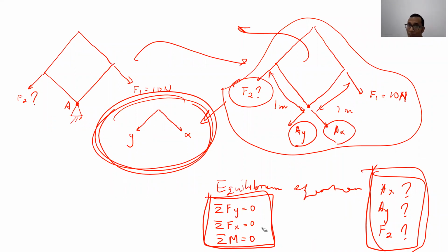Without moving the force, actually, you can solve this using sigma Fx equal to 0. Sigma Fx equal to 0 means that the total force in the x direction will be equal to 0, right, Marsha? Yes, sir. Would you mind letting me know which forces are going in the x direction? The F1. F1, okay. So we have 10 Newton. So for example, positive is like this, okay. X positive is like this.